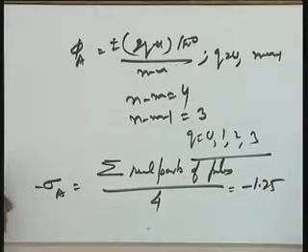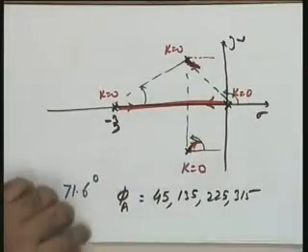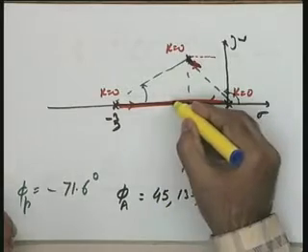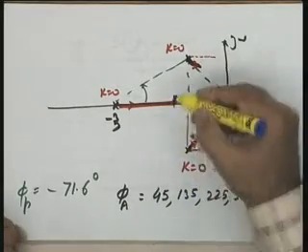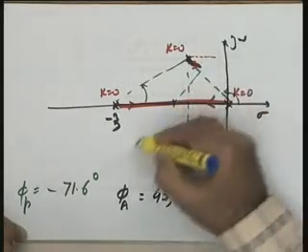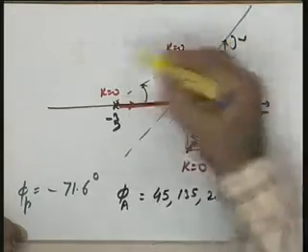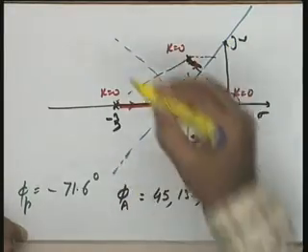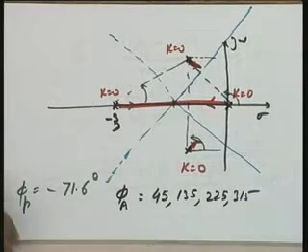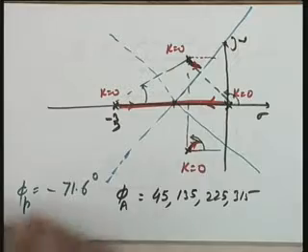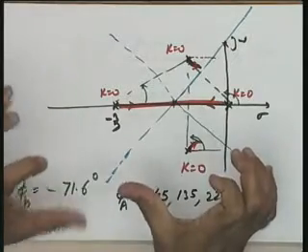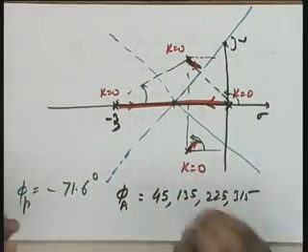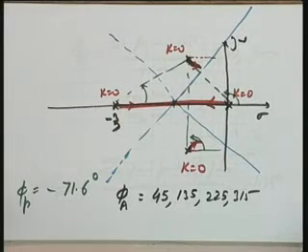So, it means your asymptotes now are available at minus 1.25, somewhere here, with these angles. Are you getting an idea now with these asymptotes before you as to what type of root locus you are expecting? After all, these asymptotes are the 4 directions for the root locus branches, there is no zero available.